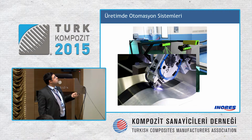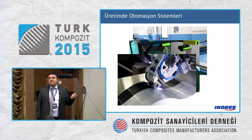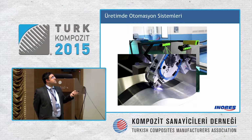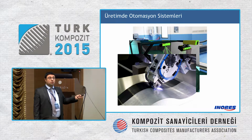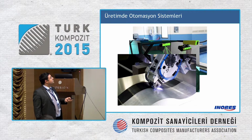One is automation for production, an automatic ply cutter. You need to define what kind of fabric, what kind of ply you want, and the automatic cutters give you the least waste and the best solution. And you can use laser indicators for your production. That will prevent wrong materials or wrong orientations, so you will solve the problems in advance.